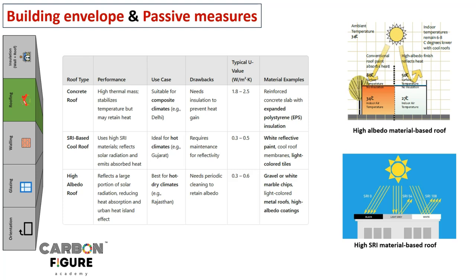So that is what they are indicating. So in your building, in walling or roofing, in whichever of your interior spaces needs these kinds of effects, accordingly you can prefer concrete or lightweight blocks or lower thermal mass material. So accordingly you can regulate the heat flows inside the different spaces of your building, right? So that's what I wanted to mention.